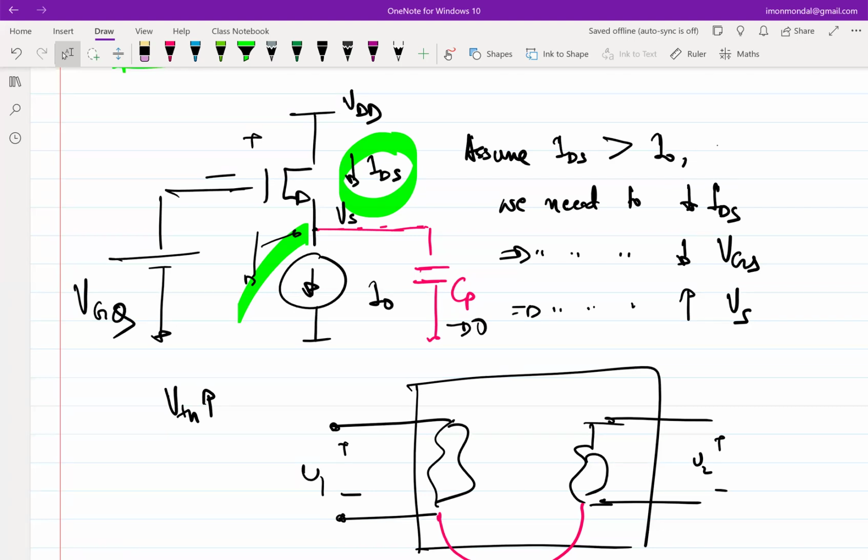The next thing that we need to figure out was in the assignment. Let's say I don't want to connect a current source. The issue with current sources is similar: you cannot have floating current sources. Sometimes you have only one current source, just like you have one single battery, and you use the same current source to bias all transistors.